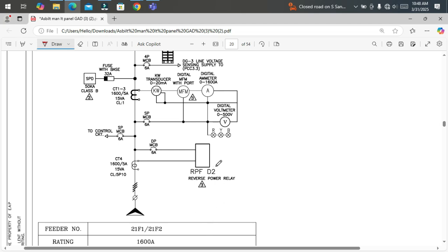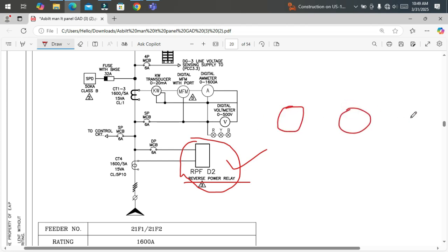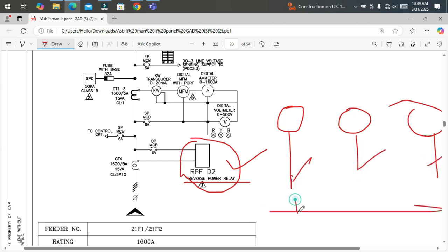So one point over here, this is the reverse power relay. So this relay is used where we have, like in terms of here LT panel, where there are 3 DG, so all are operating in parallel mode, means all are feeding to common bus bar, means they are all in synchronizing system, means parallel.